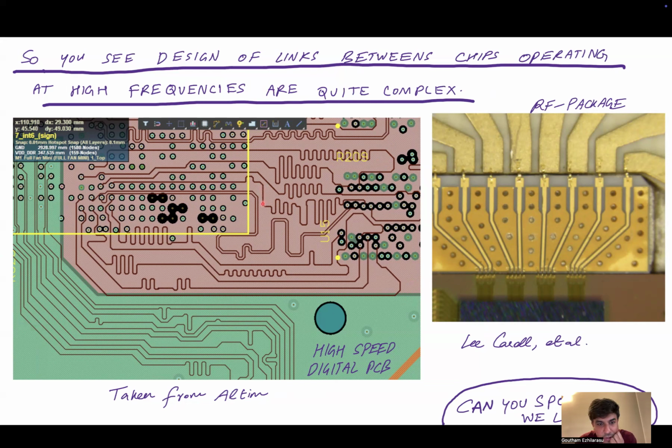You can see here that whenever you have a bend in the line, you don't have a sudden 90-degree bend, but a 45-degree bend, and that reduces the reflections. And you also notice that some of the links, if you have like three links here, have a whole bunch of serpentines added to them.